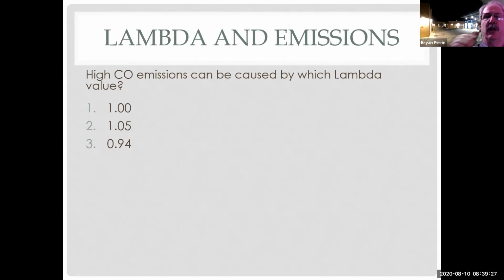And unfortunately, a lot of people replace catalytic converters trying to get a car to pass smog when there's nothing wrong with the cat. I can't tell you how many times I've seen customers make their problems worse by taking a factory cat off and putting an aftermarket one on, trying to get their car to pass smog. And all they've done is create more problems, because there's nothing wrong with the original cat.